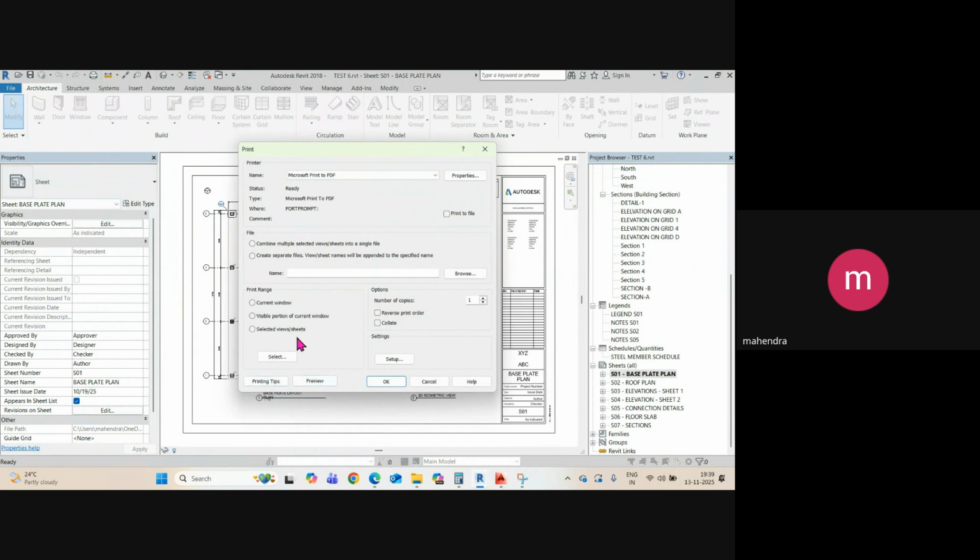So if you want to update the CAD file but your Revit file is not going to be used in future, you can update your CAD file. But mostly we keep the Revit file as the base file. So you should first update your Revit file, do the changes in the model drawings, and then export again to CAD.